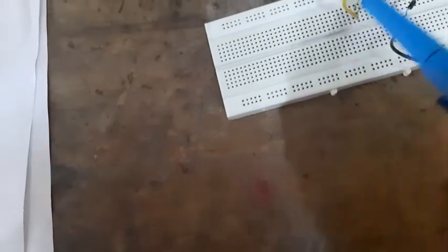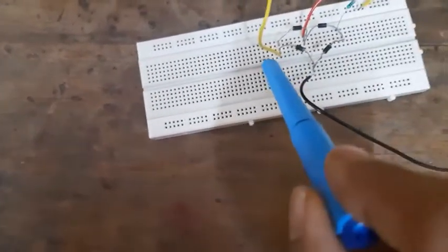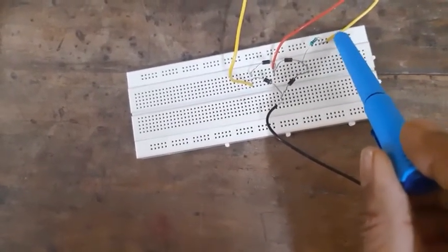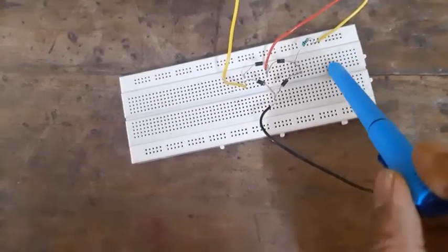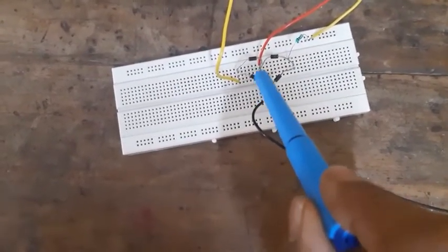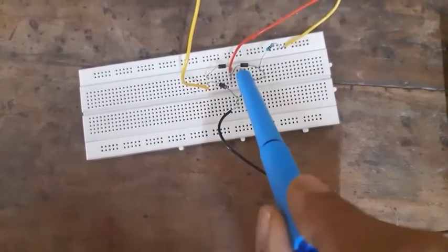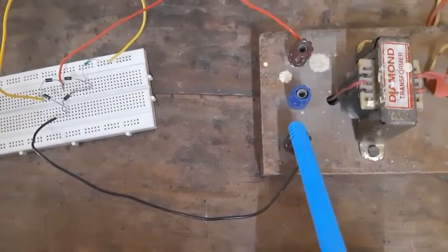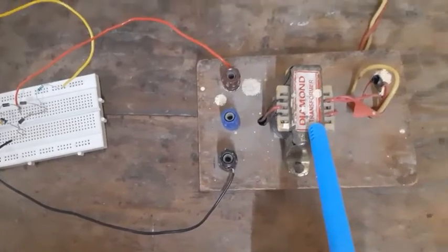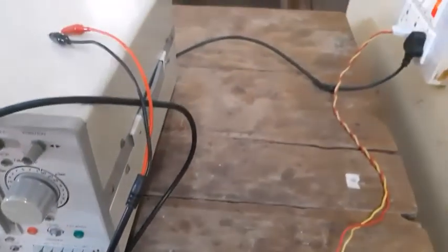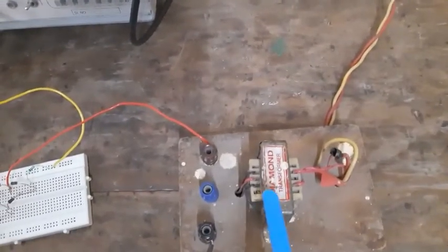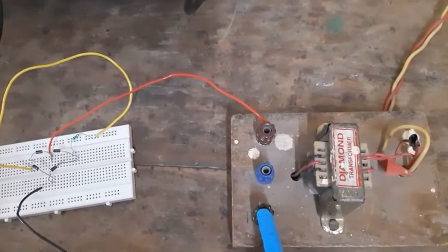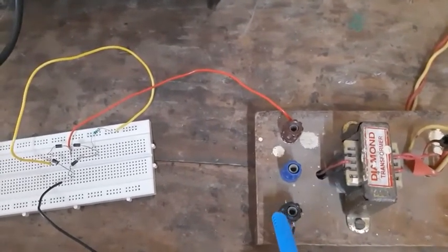So this end where the two terminals of the diodes are meeting is connected to the resistance. So these are the connections for the bridge rectifier. Here you can see the 4 diodes are connected in the bridge shape. The AC input is applied from the secondary of the transformer. To the primary of the transformer, the AC is applied, and the secondary of the transformer contains the reduced voltage, reduced to 12 volts. So actually here we are using a step down transformer.